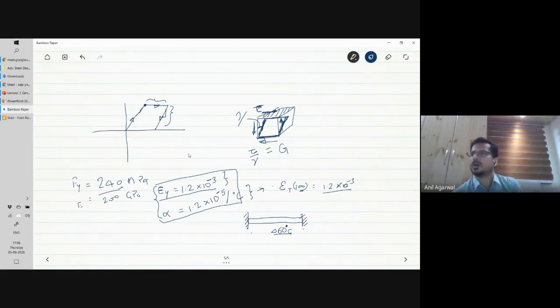So those rails do buckle all the time. So you have to find a way so that they can undergo that kind of stress. Those rails do undergo, like, 60% of the yield stress; they reach that level of stresses. But other than those structures, typical structures that we deal with.